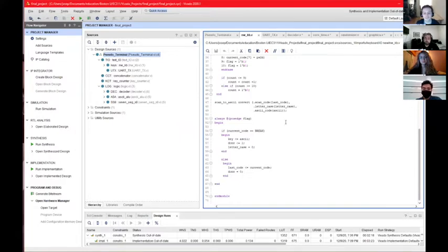The way the PS2 codes are sent from the keyboard, it's key code, break code, key code, repeat. But what was happening was it was ending up repeating too many keys to the UART, and we were getting a lot of data streamed in. So I ended up rewriting it so that if the current code is a break code, it sends the output of the ASCII code of the last code read. And that made it so that we could accurately read out the data keys one at a time.